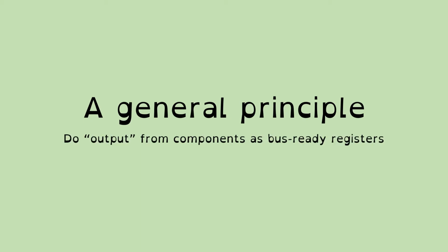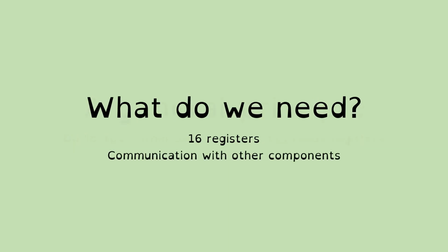When we have a component that has any form of output, if it seems reasonable, and it probably will most of the time, we're going to use an internal bus-ready register in the component to do that output. So in terms of communication with other components, we're going to need to build into our memory bank an I/O data register. This is an extra register, a 17th register.